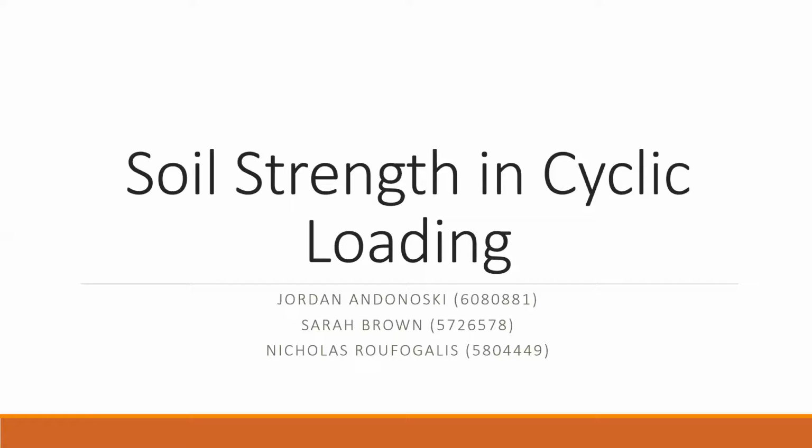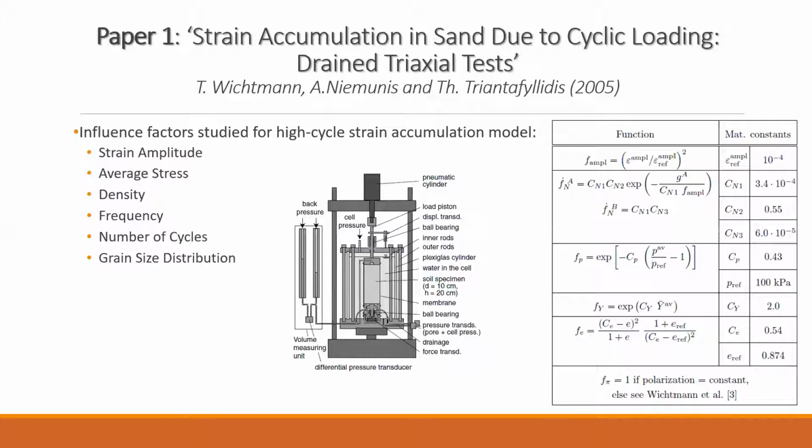also be discussed. The first paper investigated began by identifying the need for further study into cyclic behaviour of soils at a large number of cycles. The authors used triaxial testing equipment, as shown in the figure, to derive a high cycle strain accumulation model in an attempt to describe the behaviour of the soil at a large number of cycles.